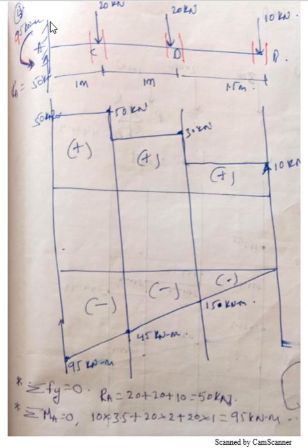Now if you consider this example, I have to draw SFD and BMD for cantilever beam wherein support is at left end. Okay, so what I'm going to do is I'm going to first calculate the reaction at this support. Actually, at this support there will be a vertical reaction and also a reaction moment. Okay, this reaction moment is not important if you come from opposite end of the support. This reaction moment will become important if you go from the end where support is there.